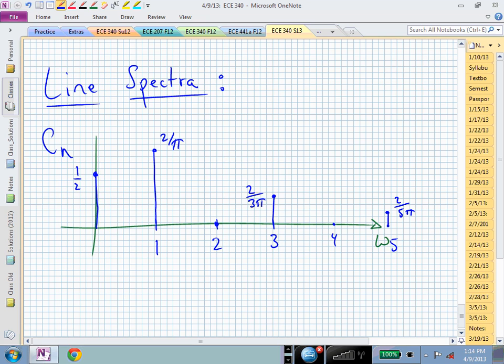And we could go on, but you can see that that is decreasing as this odd integer divides 2 over pi. We start with 0.62 and then we just start chopping it. First by 3, then by 5, then by 7. That's falling off somewhat quickly, but it's not falling off nearly as quickly as if that n was squared. So the tail on this, meaning we have higher frequency content in this signal than if there were squares on those n's in the denominator of those coefficients. Questions on the magnitude? So this is the magnitude.